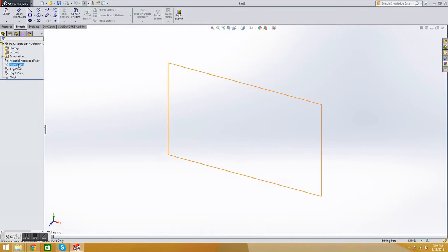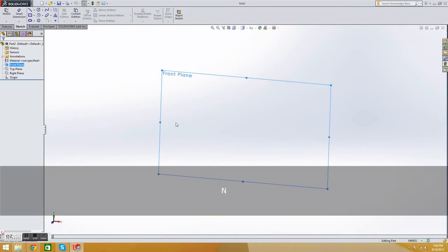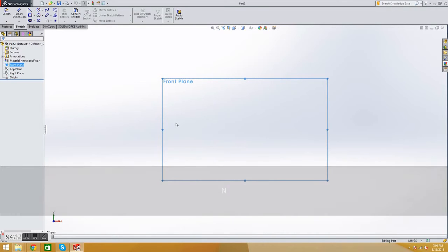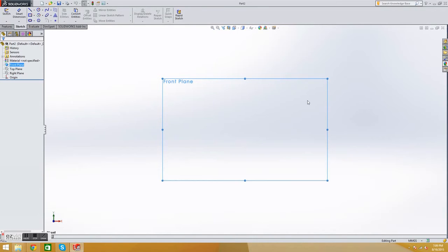Cool, so you know the basic layout of SolidWorks. What you want to do is click front plane, select front plane, see how it turns blue, and you press N to go normal to the front plane. The very first step is to design a cube, because a 3x3 is a 3x3x3 cube. Each of the edges of a 3x3 is 57 millimeters. That's just standard, so I'll show you how to design that.